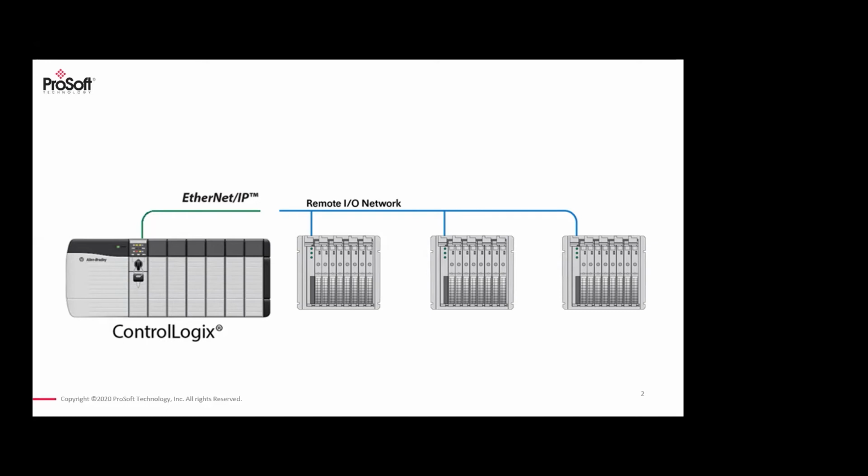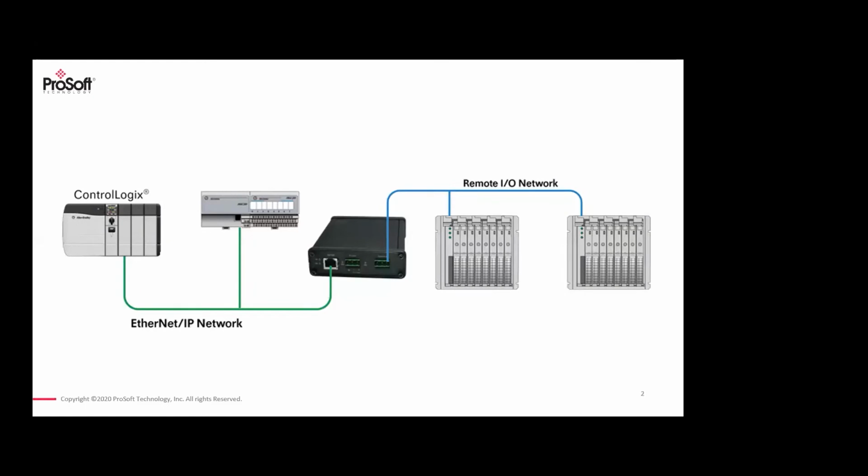And you want these two devices to interact. So we would give you a solution that sits between the two different protocols and allows for near seamless communication between the old and the new. And then you can continue to the next stage of your migration, all while using the same gateway between Ethernet IP and remote I/O, replacing the old I/O with new I/O until you finally have the entire system modernized.